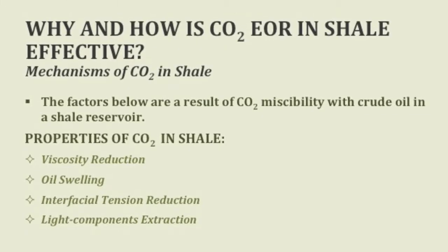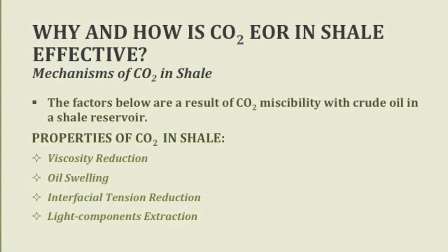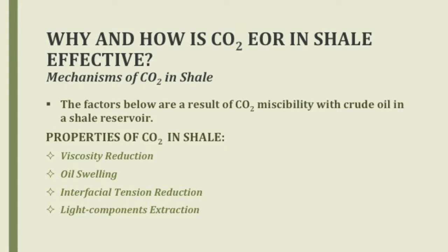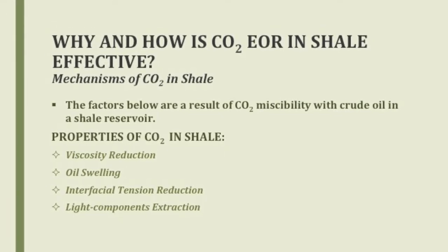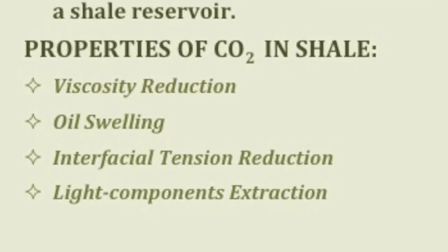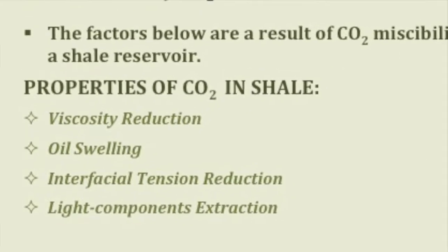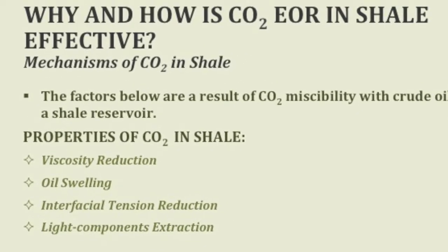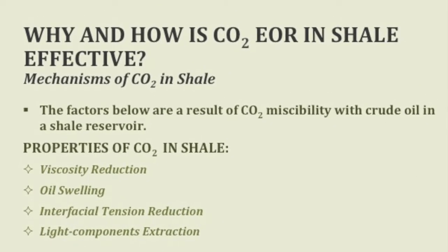Now, when CO2 is pumped into the reservoir, it becomes miscible with the oil trapped in the shale. CO2's miscibility with oil leads to a change in properties of the reservoir fluids, like viscosity reduction, oil swelling, interfacial tension reduction, and light components extraction, all of which allow for the reservoir fluids to flow more easily.